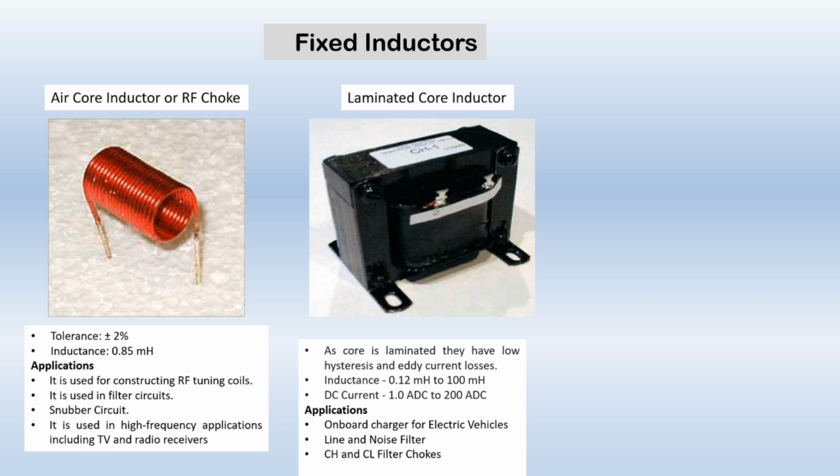Next we have the laminated core inductor. As you can see, this inductor is made by wrapping a wire around a bobbin and laminating it. The core is also laminated. So as it is laminated, it has very low hysteresis and eddy current losses.